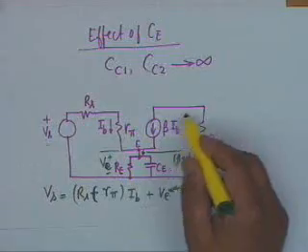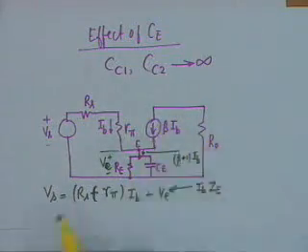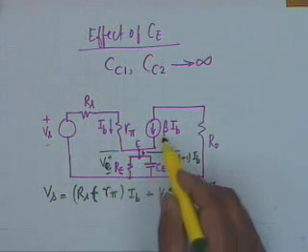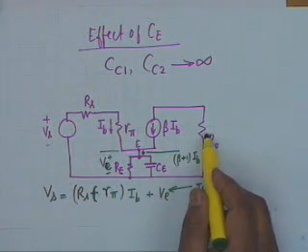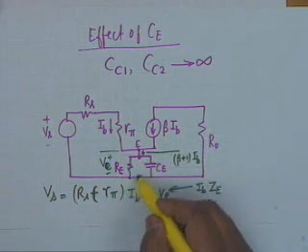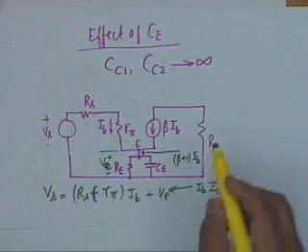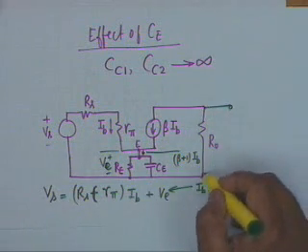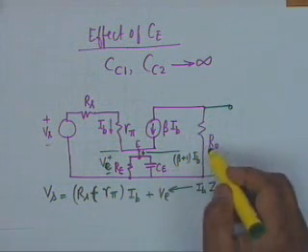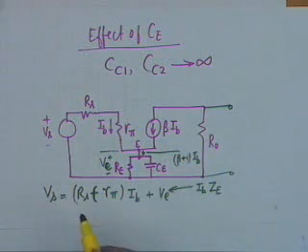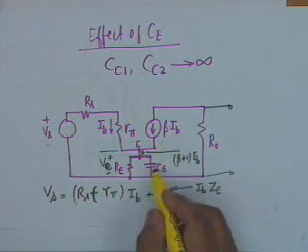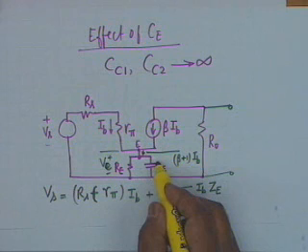Now, let us look at the output circuit. Have I really decoupled? Interestingly enough, you notice that in the output circuit there is a current generator beta IB in series with a resistance R0 and this parallel combination of Re and Ce. Now, what would be the voltage across R0? It would be simply minus beta IB R0, and therefore this is independent of what I connect here.